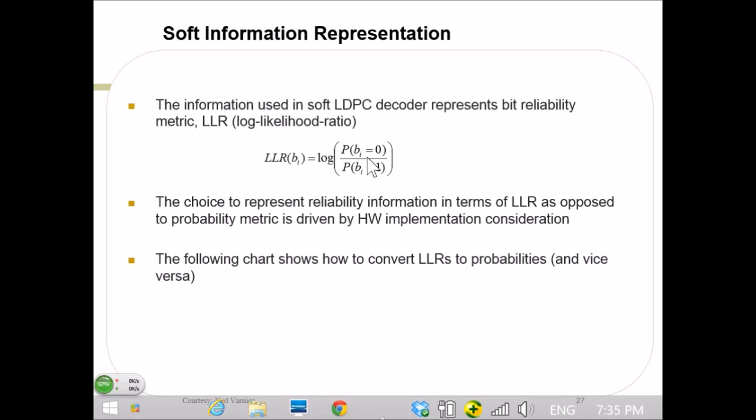Now, the LLR is going to be available naturally in most domains, but in some domains, for instance magnetic recording, we compute a log likelihood ratio based on the detector. But this happens once before starting all the iterations of the decoding, so the LLR computation is done one time before starting the decoding. Then once you are decoding, all the decoding happens in the LLR domain.